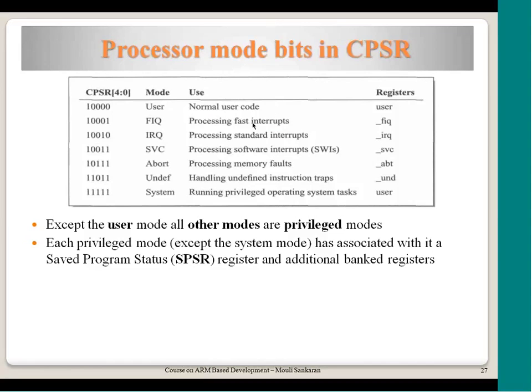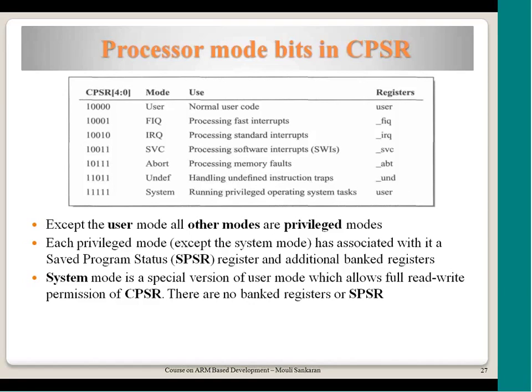Now, after the interrupt routine, when you come back, you will not get the same state of what you had prior to the interrupt. To achieve that, what ARM has done is it has made visible another register when they are entering into this mode, and automatically the hardware takes care of copying it. I am telling you this right now just to give you an idea of why SPSR is needed. But we will talk about it later on in detail.